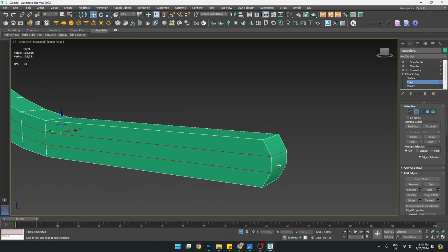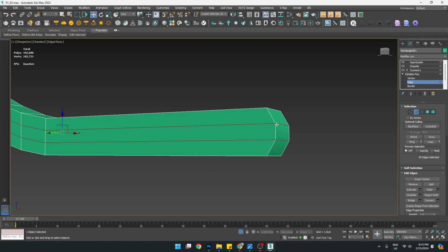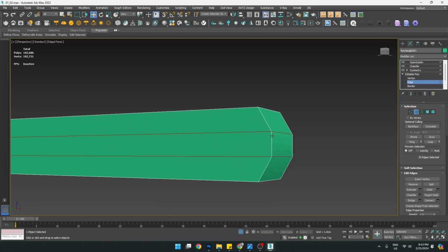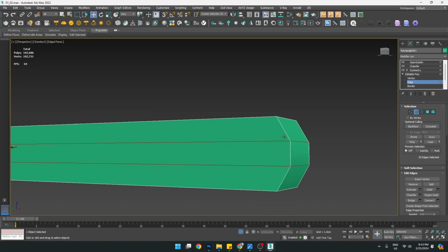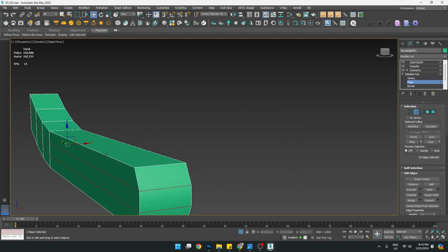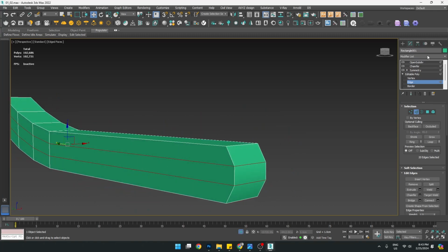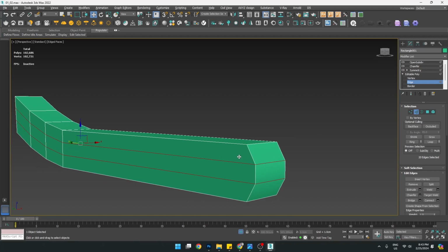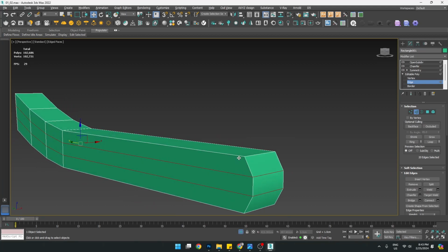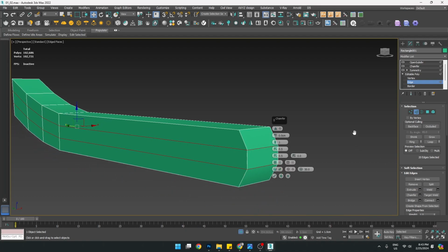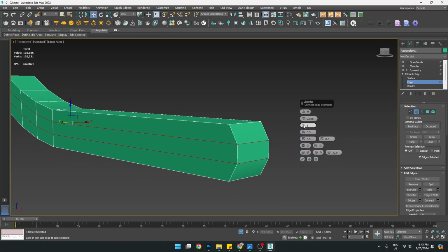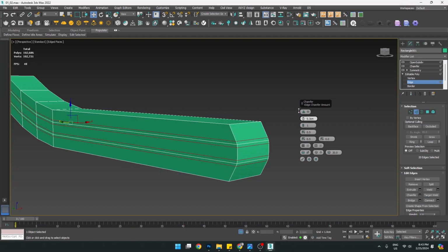The intention here is to chamfer these edges first so that it will kind of smoothen out, and then we will add the original chamfer that we have added for the rest of the objects, which will add the additional segments in the corners, and then the open subdiv also will come in to add additional softness to it. So let's click on chamfer and increase the distance.